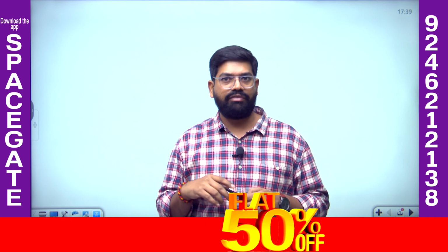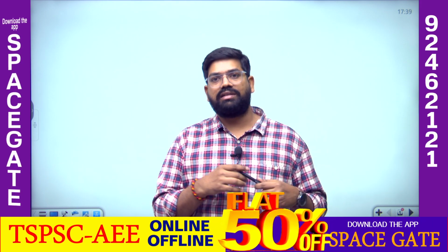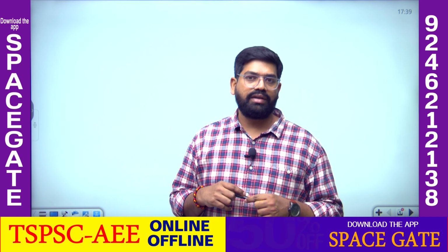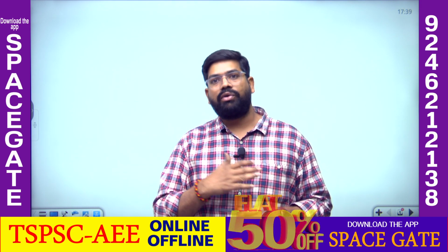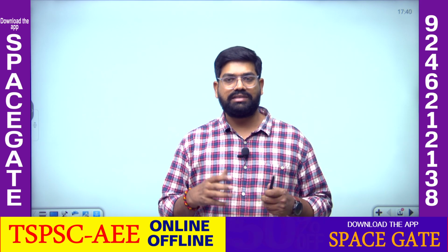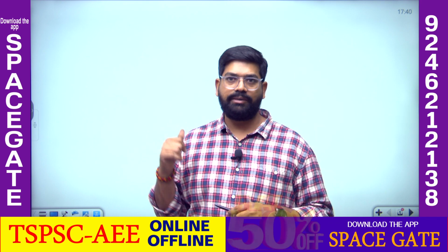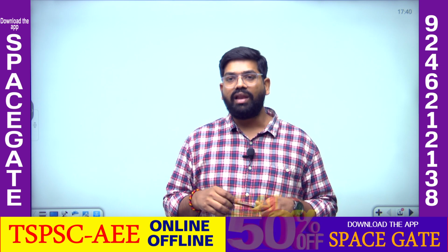Angle of asymptotes we identify by using that relation. Centroid is the intersection point of the asymptotes, right? For the breakaway point we construct the characteristic equation, and from that differentiate k and equate to 0, which will give the breakaway point. Got the point? And we even did some examples of how the root locus branch crosses the imaginary axis, the intersection with the imaginary axis, how you find the value of k and the frequency at which it crosses, which we also observed with the example. Okay. So such questions we can expect, and you should be very careful in these kinds of exams.